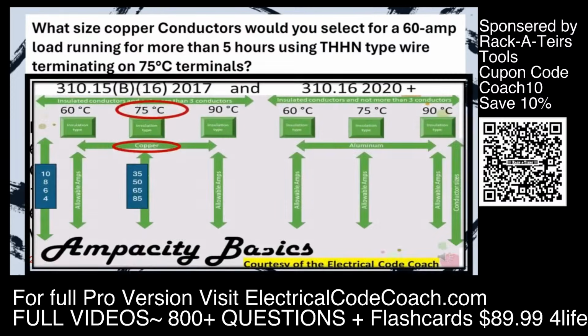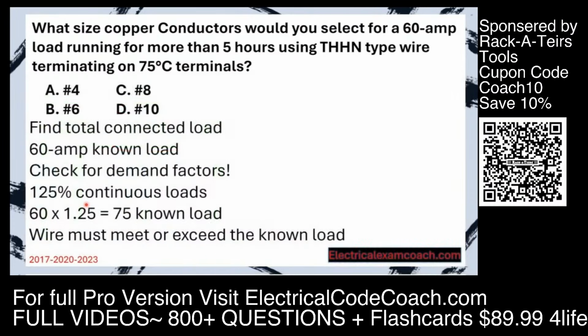We head to our primary ampacity table. We head to the copper side because it wants copper conductors. We're in the 75° C column, and we need to go down and find a wire that meets or exceeds 75 amps, and we find that it happens to be a number 4.